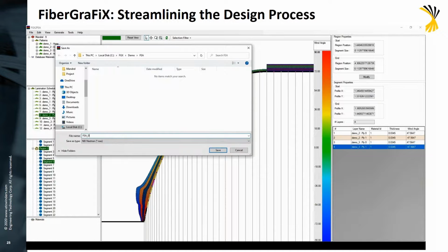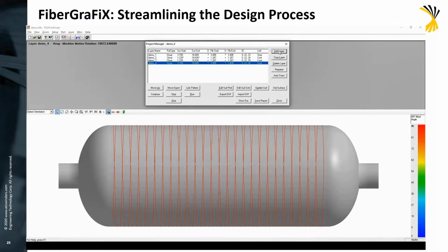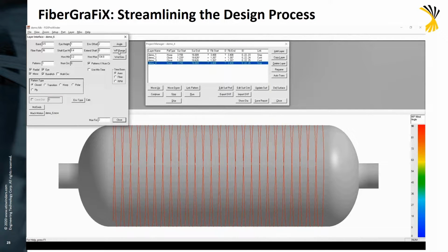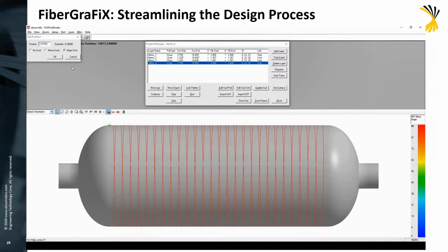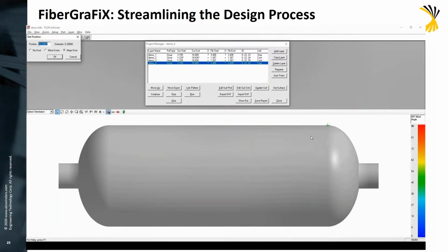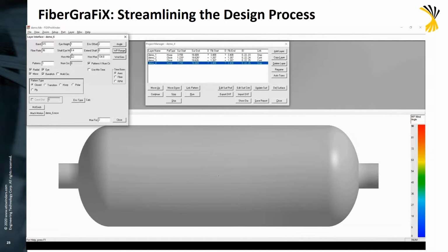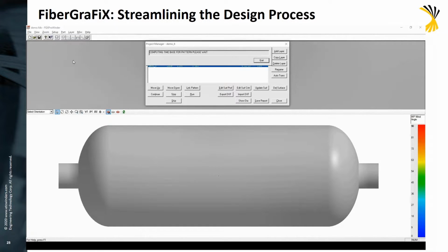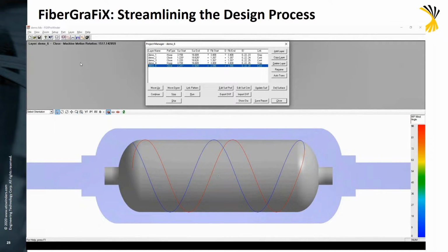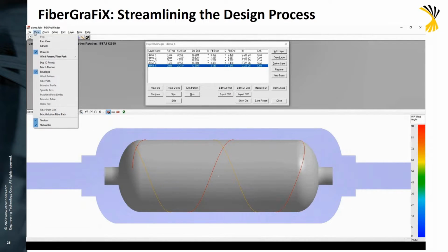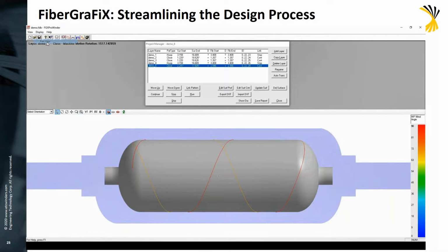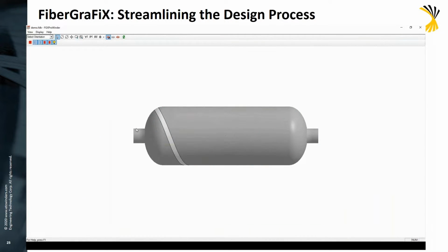At this point, the FEA analysis is performed on the shell model, and we're going to assume that based on the results, further refinement of the laminate is required. This is possible by simply changing the generation properties of a layer, or in this case, adding a new helical layer and moving it into place. This reinforcement helical will begin and end an inch below the cylindrical section, a knuckle winding, so to speak.